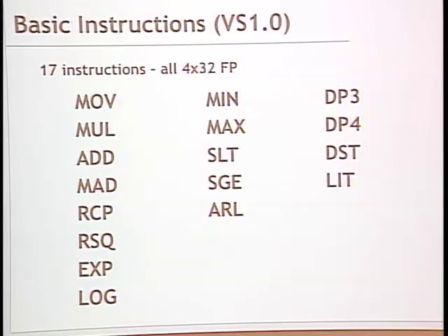This was an instruction set for vertices, and we were going to have a different instruction set for fragments. We started out doing that, with a very different instruction set for the two. As time goes on, instruction sets broaden and start getting closer together. We're moving from having 2 totally different instruction sets to having the same instruction set. We're also moving from 2 different task parallel models to a more time multiplexed model.